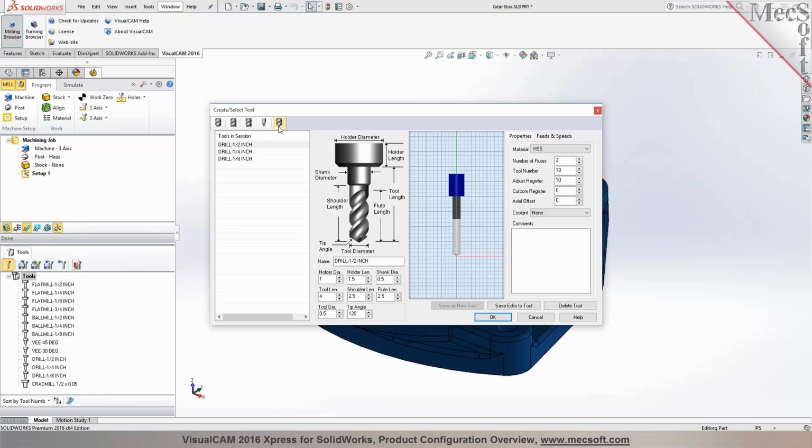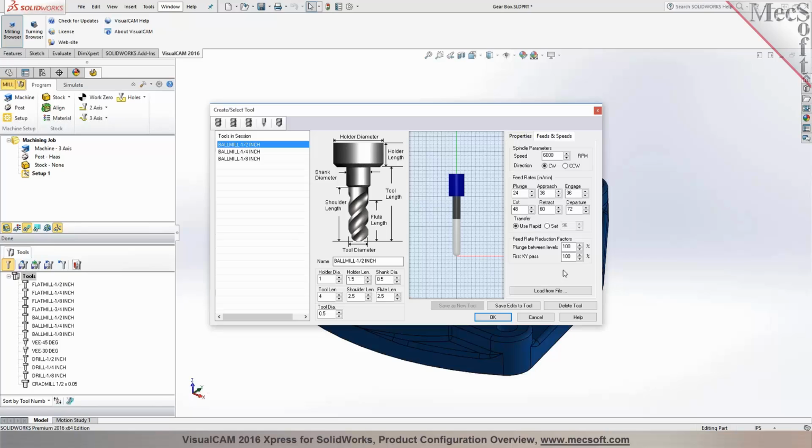Additional tool types like chamfer tools, taper tools, face mills, fillet mills, lollipop cutters, user-defined tools, and tap or reverse bore tools are offered starting with the Standard configuration, so you can upgrade to the higher configuration if you need more tool types. On each of these tool types you can specify your tool properties, assign your tool numbers, and set your feeds and speeds.